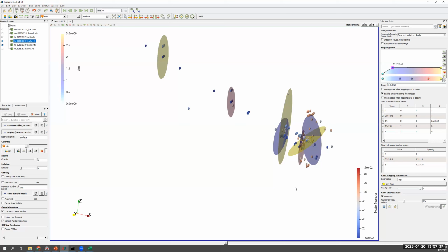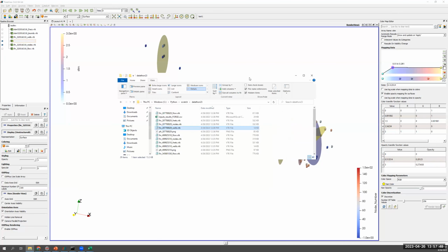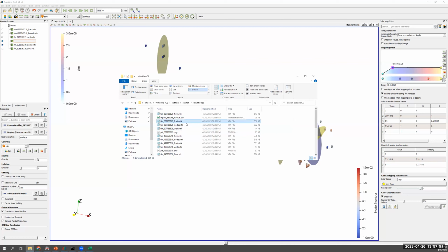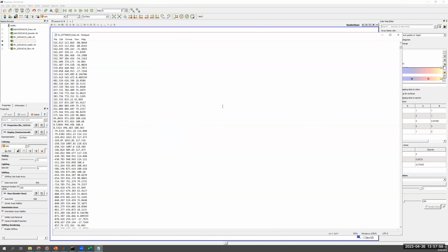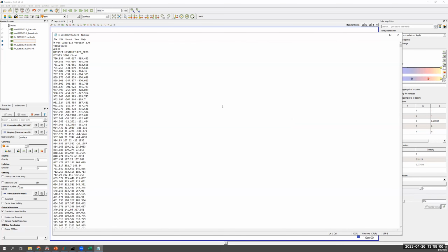So is GeoDT integrated with ParaView as the display output? The files being generated by GeoDT are VTK files, which you can see here in this file browser window. The files themselves, you can actually open them. They're just text files. This just contains geometry information and information for how the coloring should be based on, the VTK format.